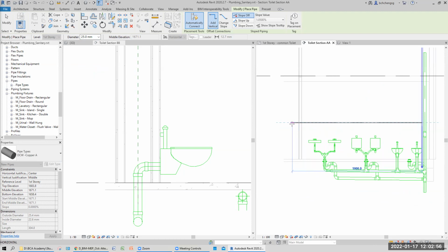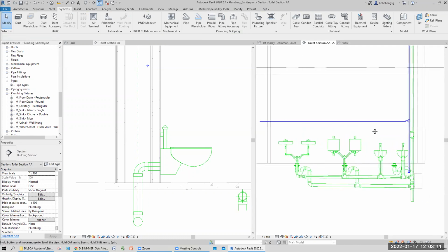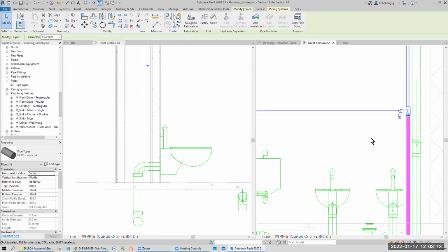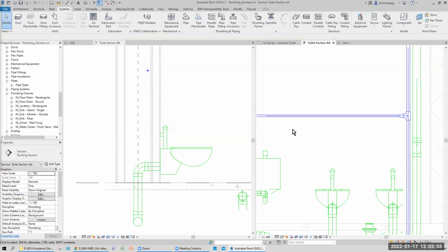Draw across one to here, extend. Why? Because this water pipe here later is going to supply your water heater. And then your water heater will come out with the smaller one. But individually, one-on-one, this is 50, this is 25. Okay, height, of course, you can set a proper height. This one 16 something. Let's say give you around 16. More value, easier to adjust. Okay, nicer that way. After that, you can draw your piping now.